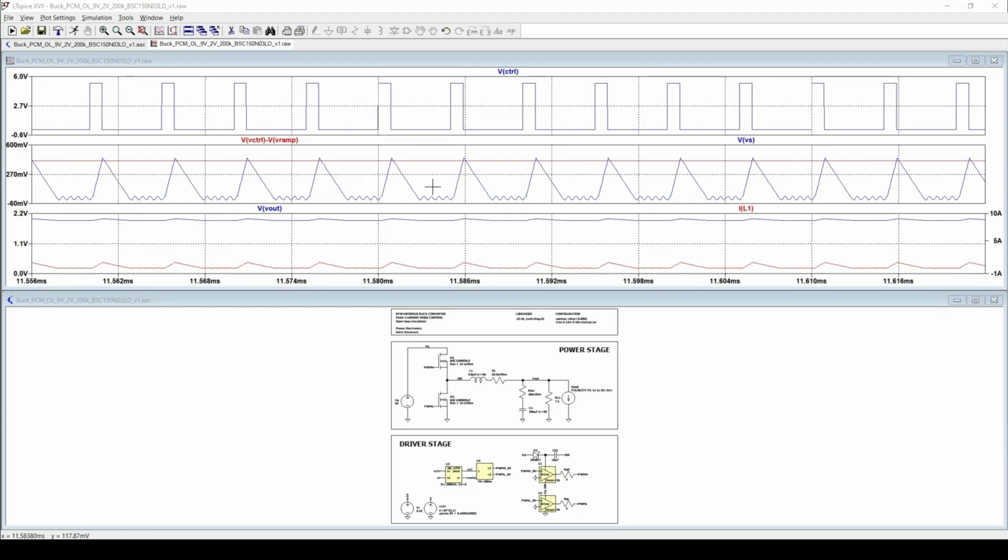However, in the literature, the ramp is very often illustrated as being subtracted from the reference. For that reason, the ramp is shown here by subtracting it from the reference purely for visualization, so its influence on the effective comparator threshold is easy to see. This subtraction does not represent the internal implementation, it is shown only to aid understanding and debugging.